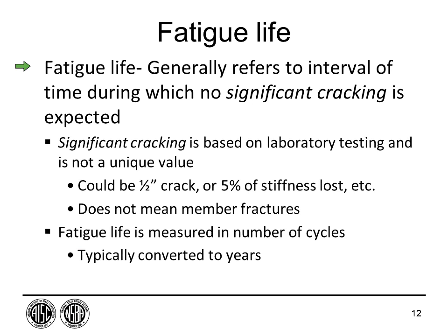How do we determine that then? Well, it's a little tricky. You can imagine that the way we get fatigue life data is actually from large-scale or full-scale fatigue tests. Right here at Purdue, we're running several right now. And those tests run 24 hours a day, 7 days a week, cycling girders or details. But eventually we have to say, enough.